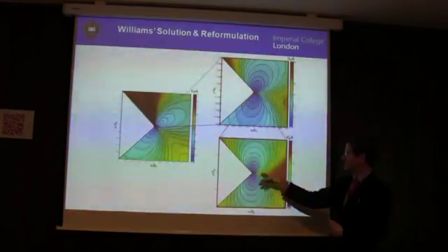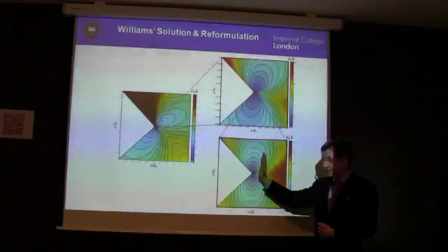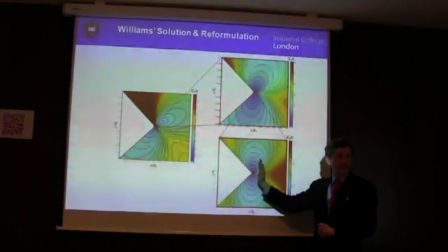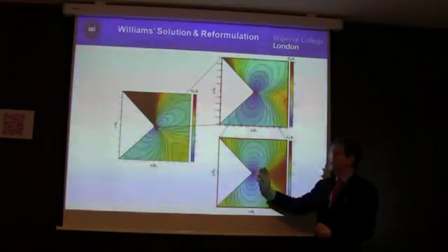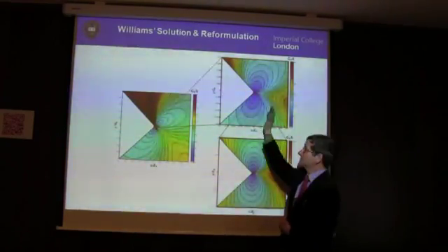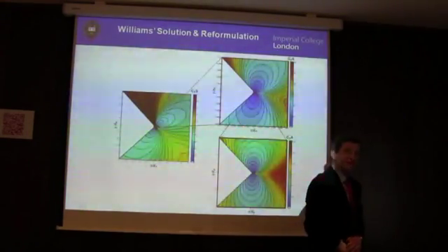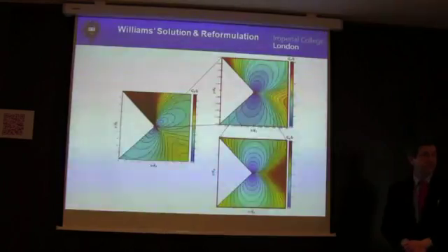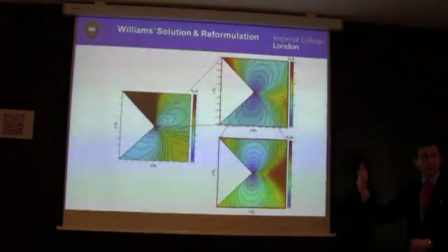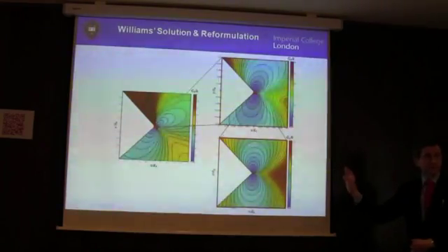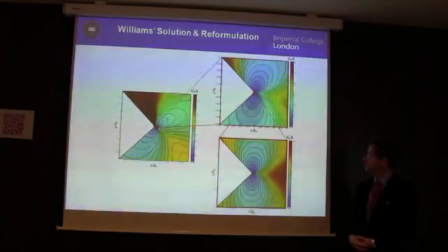and then you could see that if the loading was sufficiently small that it looked like the vertical figure of 8 that we're all familiar with, you've actually got mode 1 loading in the region that really matters, where cracks or whatever is going to start at this corner, whereas if you got the loading sufficiently high that it's turning around like this, then the crack is going to start in a combined mode loading. And the beauty of this is that you can say it all within the Williams solution. Okay, so that's where I got to 2 years ago.